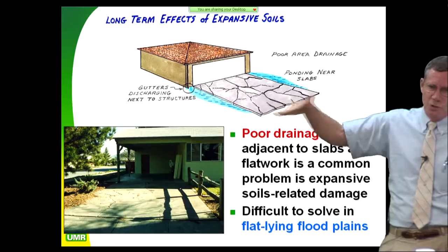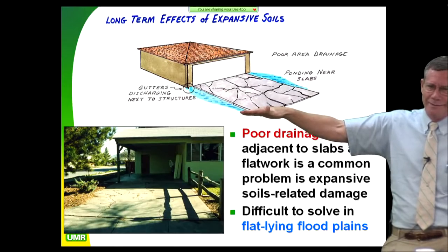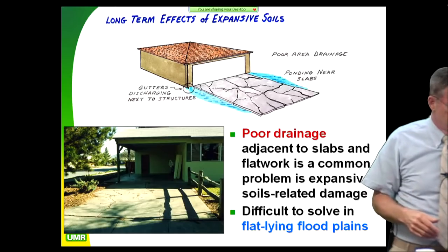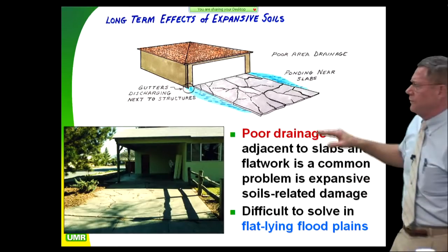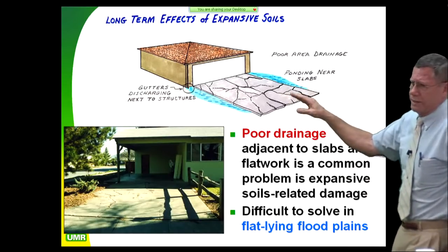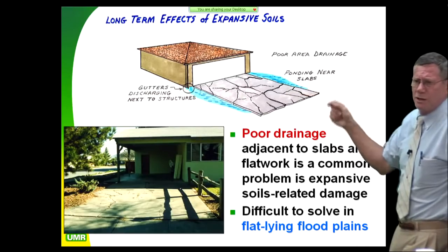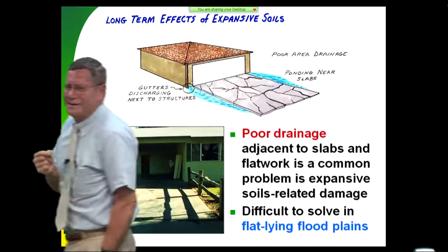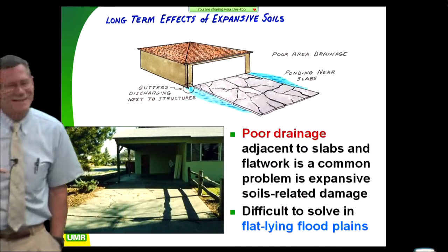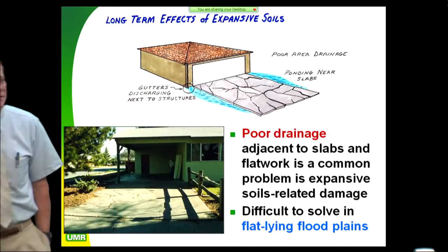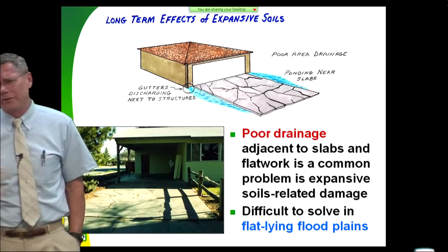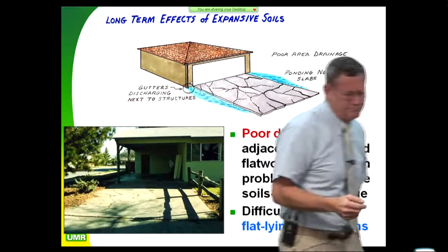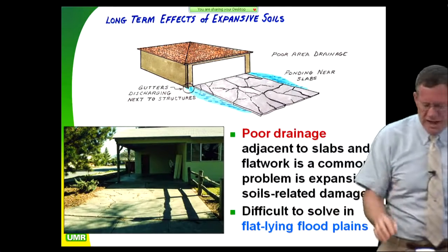You're actually sloping the wrong direction on the lot because of the natural levees. And so you're going to have poor drainage. So when I say non-reinforced, that means it doesn't have rebar. They probably have temperature steel in it, which is welded wire mesh. Welded wire mesh, contrary to what a lot of contractors will tell you, is not reinforcement. That's just temperature steel, and it's not worth a whole lot. It's better than having nothing, but not much better than having nothing. It's close to having nothing.